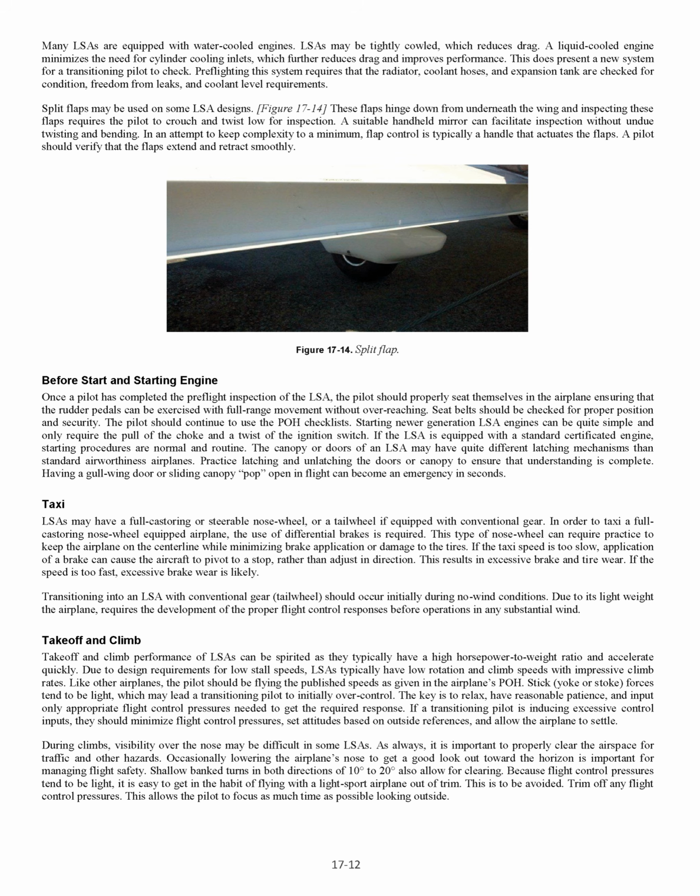Taxi. LSAs may have a full castering or steerable nose wheel, or a tail wheel if equipped with conventional gear. In order to taxi a full castering nose wheel equipped airplane, the use of differential brakes is required. This type of nose wheel can require practice to keep the airplane on the centerline while minimizing brake application or damage to the tires. If the taxi speed is too slow, application of a brake can cause the aircraft to pivot to a stop, rather than adjust in direction. This results in excessive brake and tire wear. If the speed is too fast, excessive brake wear is likely.